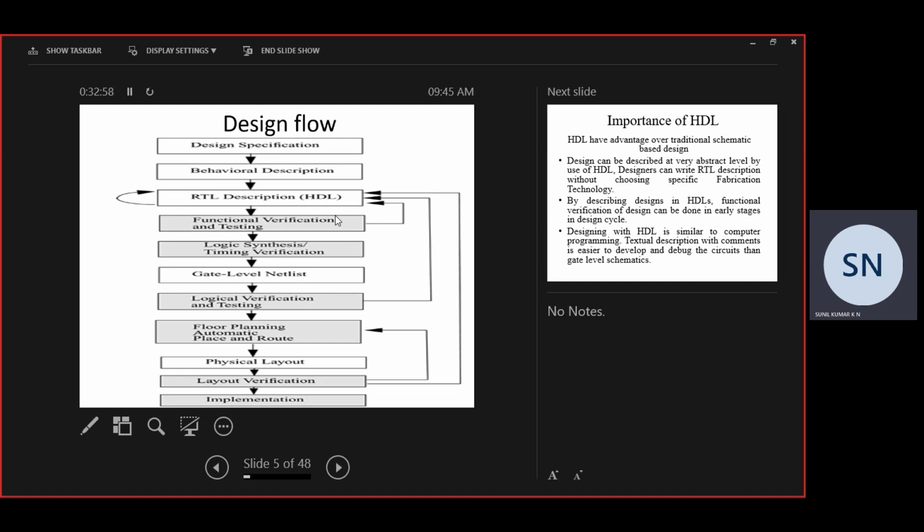So again, P2 drain Y1, source power, gate B. P3: output is Y, source is power, gate is Y1. The same way N1, N2, N3.